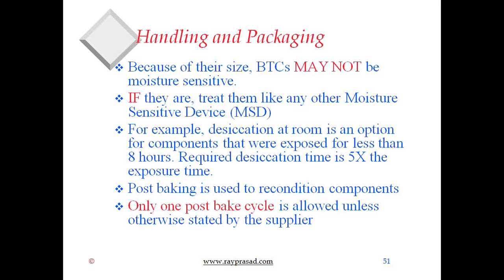So what normally you should do, there are a lot of ways to deal with it, when you open the package, take out what you need, seal it back, and you haven't started the clock for that. Or just have some mechanism that you open the package. If it's open during the day, then you have a running total that you keep track of. If this was level 3, that means you could keep it open for 168 hours. And well, then you have to keep track of how many hours it was open in the meantime.